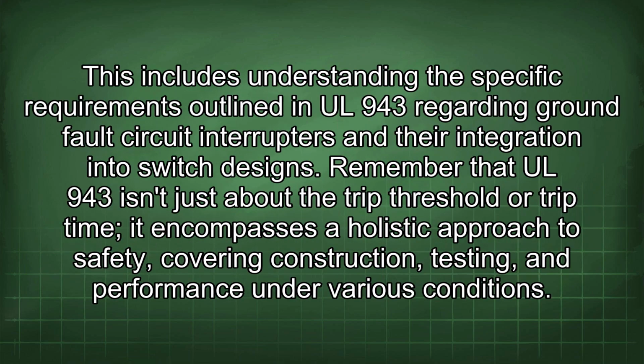This includes understanding the specific requirements outlined in UL 943 regarding ground fault circuit interrupters and their integration into switch designs. Remember that UL 943 isn't just about the trip threshold or trip time; it encompasses a holistic approach to safety covering construction, testing, and performance under various conditions.